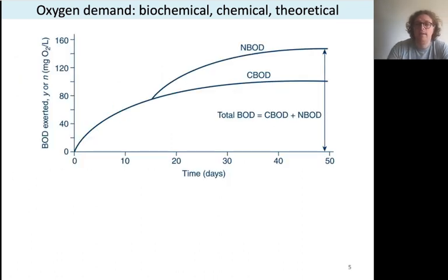So if we think about how these are going to look through time, the NBOD exertion, so when that reaction is actually using oxygen out of the water column, tends to be a little bit delayed compared to carbonaceous BOD. Notice our BOD5 that we looked at really early on is primarily measuring the carbonaceous component. And so if there's going to be significant NBOD, it wouldn't be captured in a 5-day test. In that case, we often use a 30-day test where we can start to capture some of that NBOD as well. So 30 days being the incubation time in your laboratory, for example.